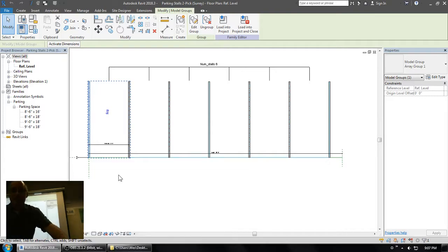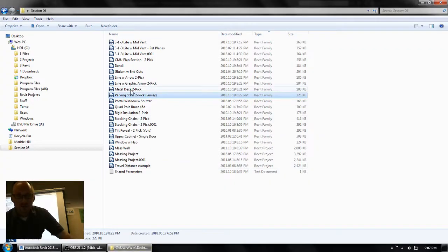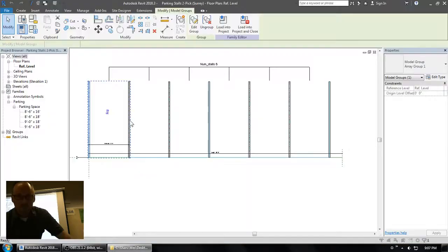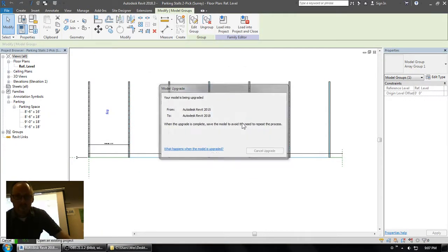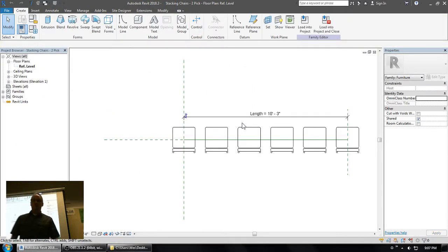Now if we contrast that with the chairs, there's the first pick, there's the last pick, and Revit just fills the space in between with an appropriate number of chairs so they're at least not overlapping and not over top of each other. This was done using the last type array. You can dig into those and play around and see how those values worked.